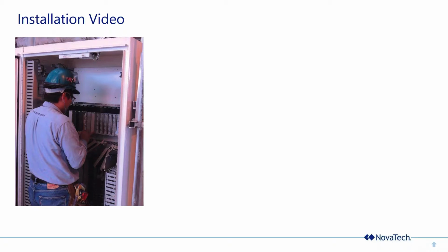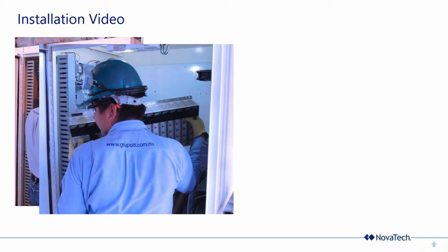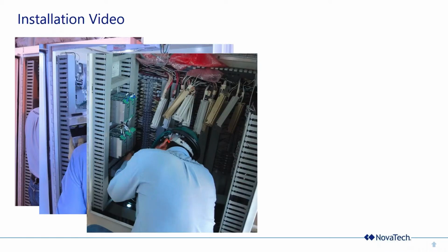Sometimes they start off doing the removal, and by the time everything's removed, they move into the role of doing the wiring. We just find that speeds things up and reduces the amount of training when we are supported by additional local people. Here he is taking out the quantum I/O rack, and you'll notice that he's got all the quantum I/O modules still in it because he actually took out some screws that held the module. He put the modules back to keep everything neat.